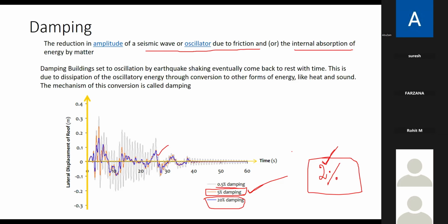It again depends on the stiffness. If I have more stiffness, the building itself will control the torsion, isn't it? If I have a flexible building instead of a stiff building, there is a lack of stiffness, but at the same time it is satisfying the code requirements in terms of drift as well as time period. Let's move forward to check further for torsional irregularity, because you are not going to limit your buildings to checking only the time period, drift or displacement. You have to move on to further checks as well. We will see that while you are doing the live model.